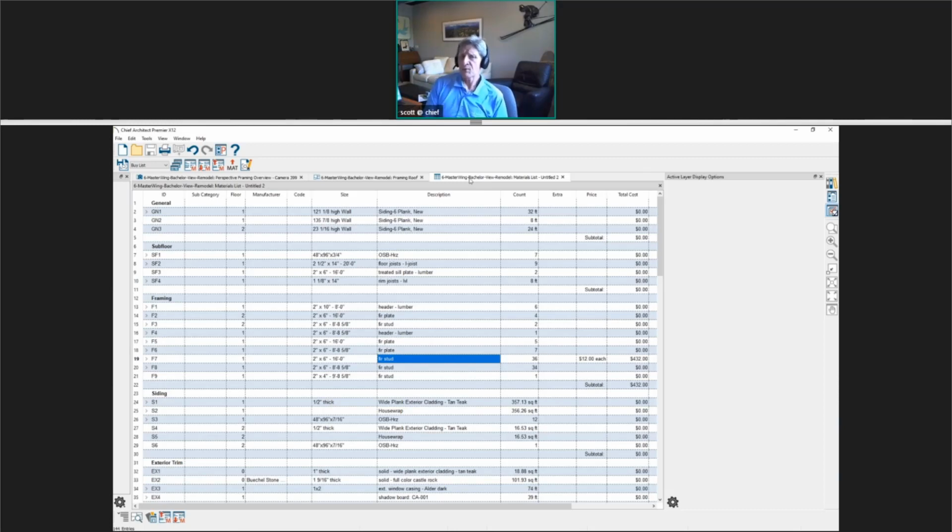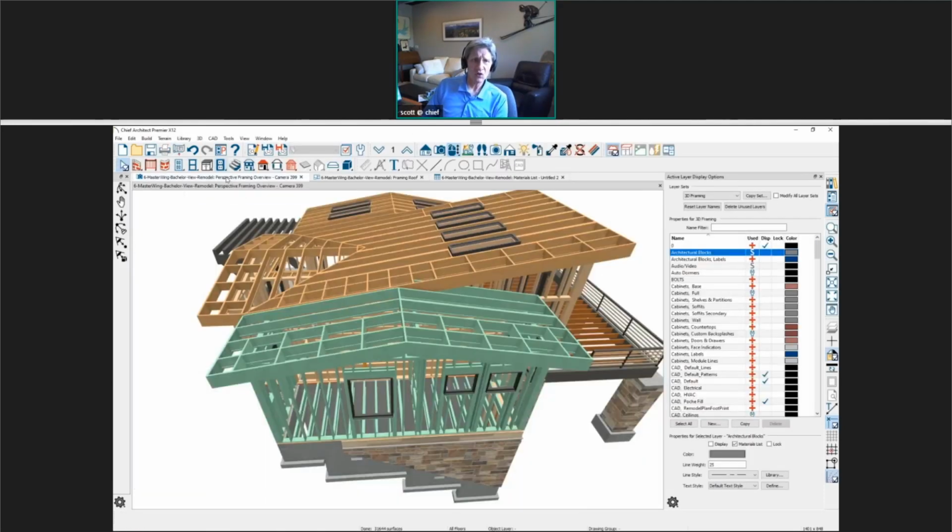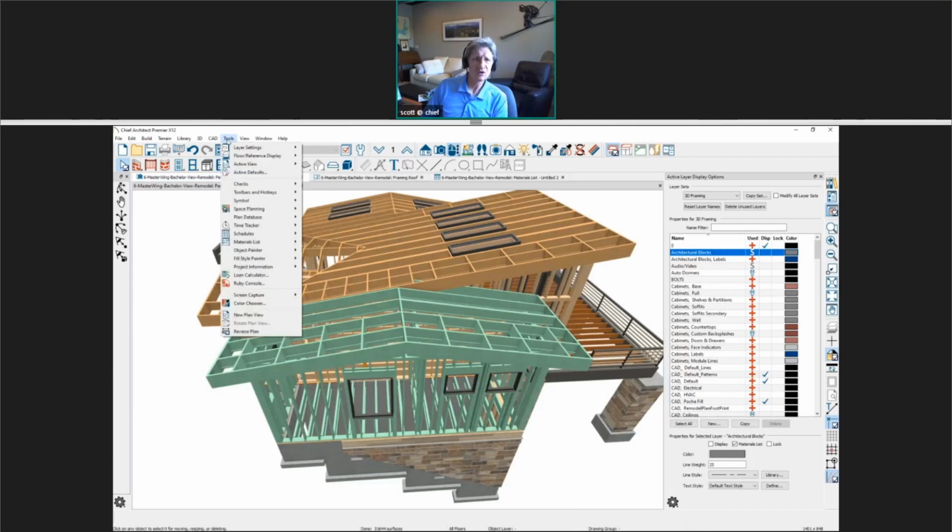When I began my plan here, Norman, I used the imperial plan template, and you're seeing the results of using the imperial measurements. We do support having a metric plan template, and when you're using that, you can access your units in metric. Also, you can control that if we just switch back here and go into our structural member reporting that you'll find underneath materials list.